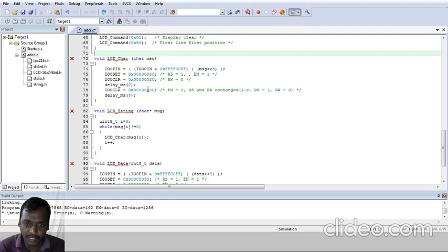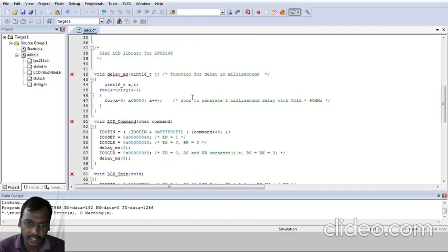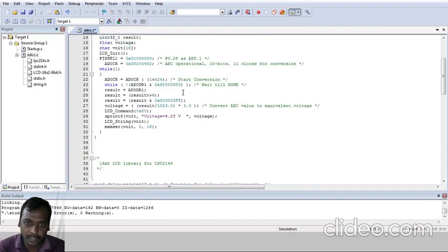Close the loop. That means here the write operation is performed whenever 8-bit data is received, that time the enable starts the IC operation. Here observe the main program. What does it do? Whenever 8-bit data is received, internally it performs the successive approximation ADC operation to receive the analog data and convert it into digital form.